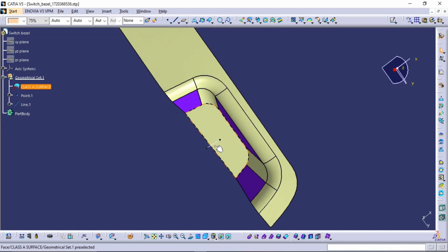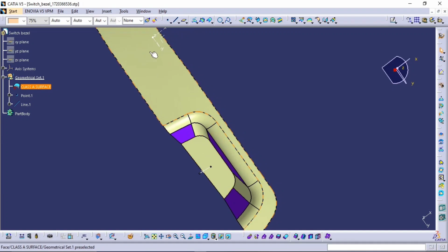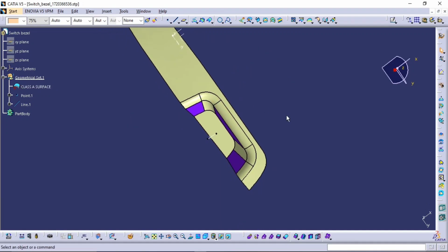Okay, what does it mean? When you have a tool direction like this, a tool axis like this, your molten plastic material will flow in this direction. So in this way, the molten plastic material will reach every single corner of the mold part very easily.